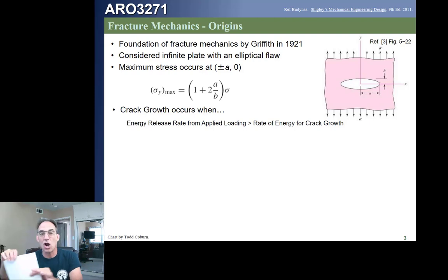Now, as this gets larger and larger, let's say like the skin of an aircraft, where it's hard to define what width of the skin is there because it goes beyond where I'm really focused, then that has the idea of a far field. The far field stress is just the P over the total A, whatever the stress level is uniformly through here. If somebody has a hole right here, we're going to expect a stress concentration, but the far field stress is the stress as if there was no hole. Normally, when looking at stress concentration, we take the net stress first and then apply the stress concentration factor. Far field stress has the idea that we calculate the stress level as if there's no feature, no interruption in the part.